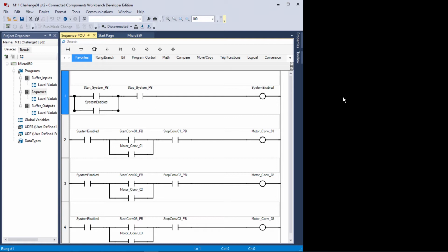A toggle Boolean is just a straight up change the state from whatever it is. If it's off, make it on. If it's on, make it off. It's not a double like a push button. To press it, release it. We're going to show you that logic. It's called self-extinguishing logic, and I use this logic a lot in real processes because what it allows me to do is, when a memory location goes true or on, a true if on instruction reads it as true, initiates an action, and the logic itself turns that bit off that we used to turn it on. So I'm going to add that rung of logic.